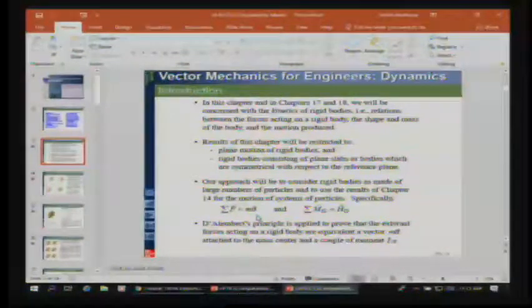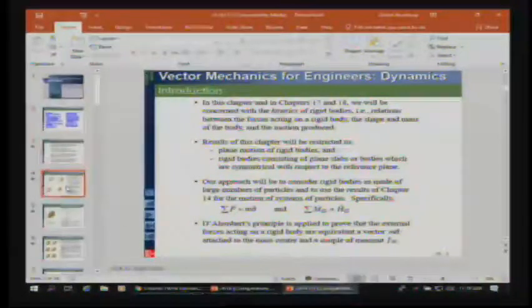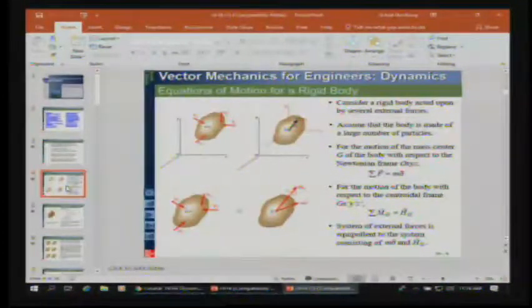All right, so the next thing that we mention for the first time is D'Alembert's principle, which is basically what we're talking about here. We're going to show that the external forces acting on a rigid body are equivalent to that inertia vector, m times a-bar, at the mass center, and the couple I alpha. So this is just that idea of transmitting forces on a rigid body to another point, and expressing forces as a force plus a moment. We did that previously with rigid bodies when we were talking about couples and force couple systems. So this is just extending that idea to something that looks three-dimensional.